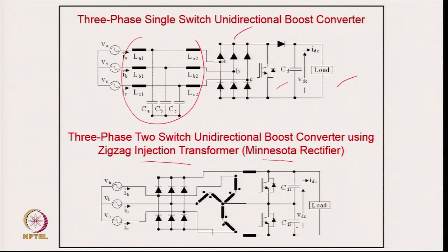You get low harmonics here, of course, and unity power factor on this side, if the load needs only DC. It provides boosting features because you have a boost converter here. Apart from that, it has a very interesting feature: if you require 2 equal voltages across a DC load, similar to a switch reluctance motor drive midpoint converter, you can provide this from this converter also.